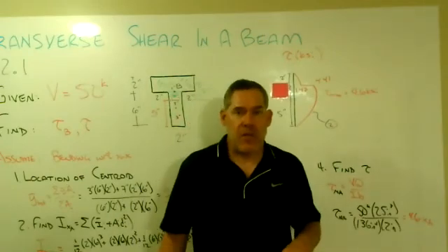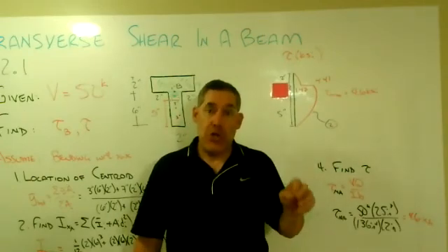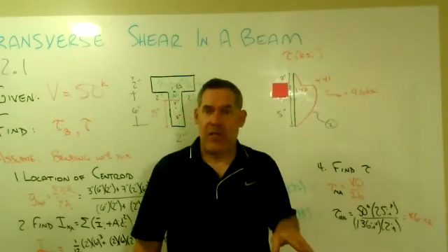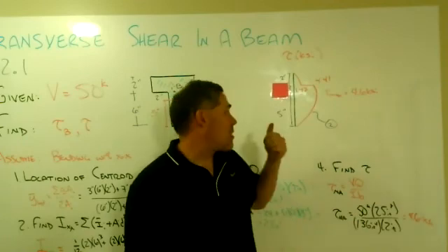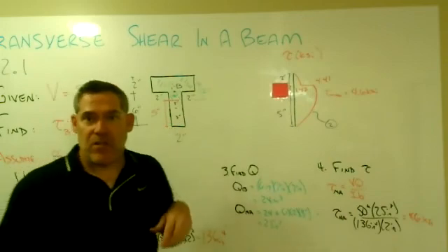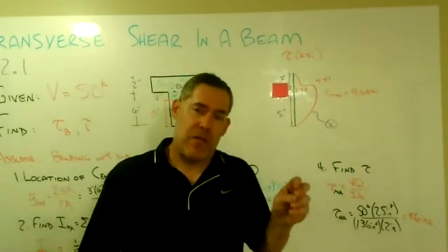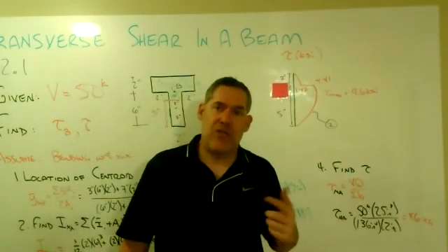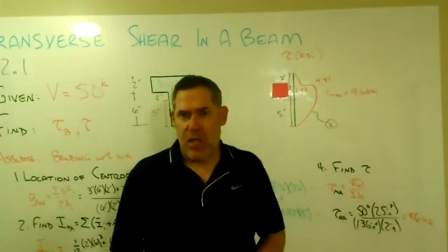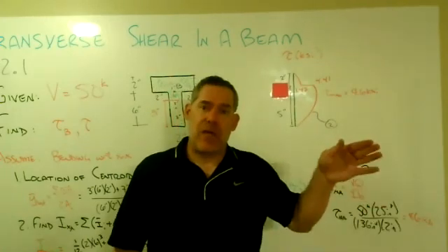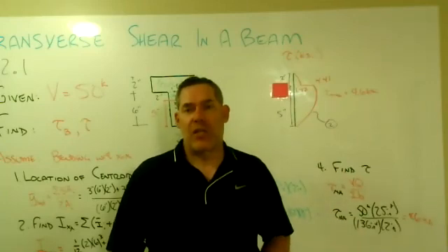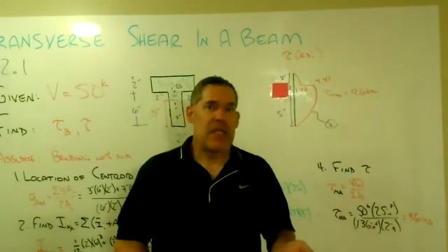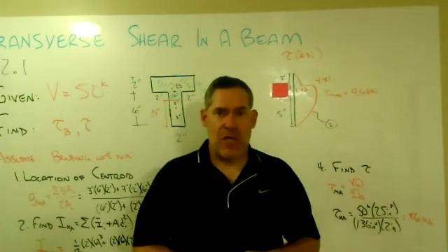In most typical beams, they're going to be dominated from a strength standpoint by the normal stress and not the shear stress, right? If this was all about shear stress, then we probably wouldn't be designing our beams to look like this. It might look like something different, right? But typically the first thing that we have problems with in beams from a strength standpoint is related to the normal stress as opposed to the shear stress. And so we'll design for the normal stress, and then we'll come back and check to make sure that the shear stress maximums and variations are acceptable. And usually we'll be okay, except for in certain special situations, which you'll get into later.